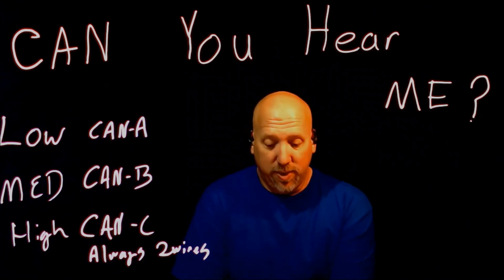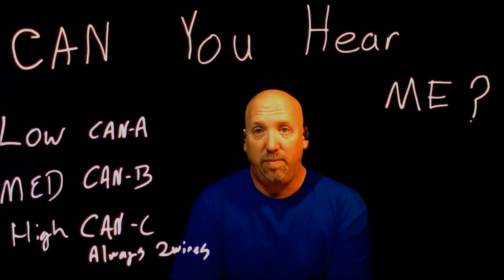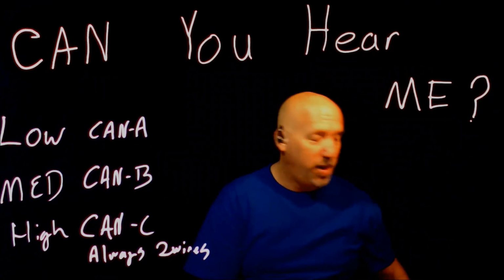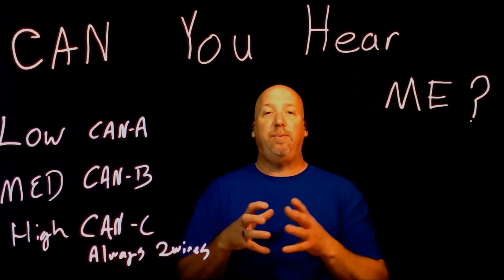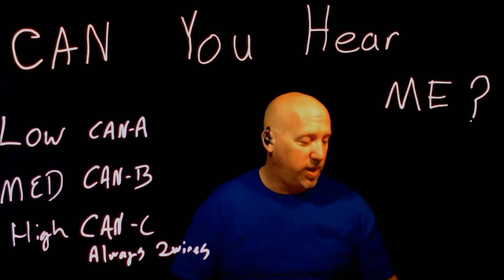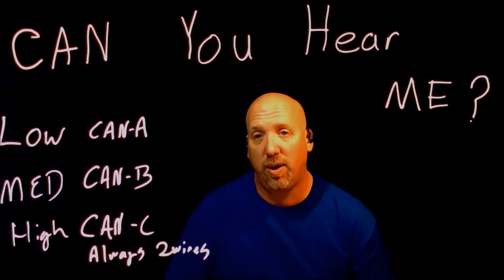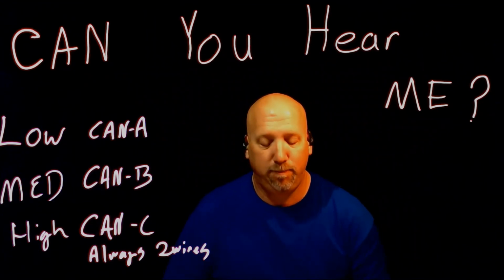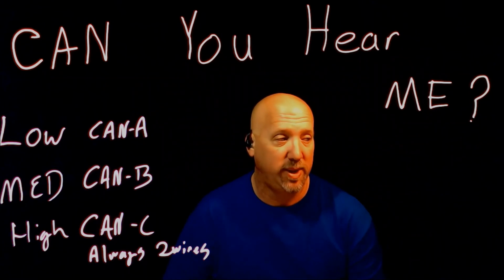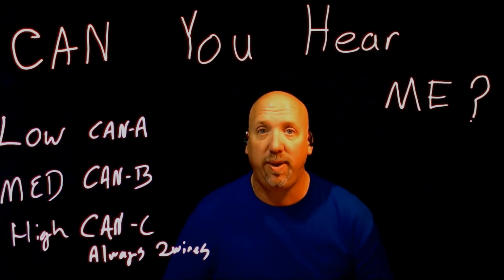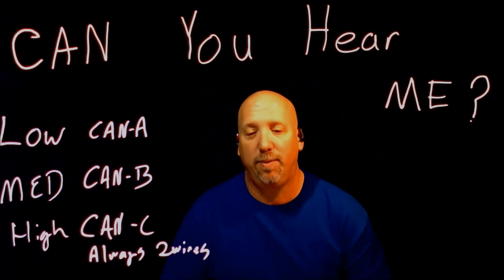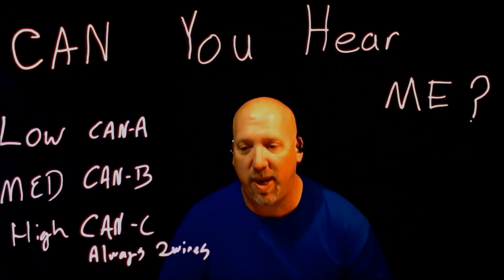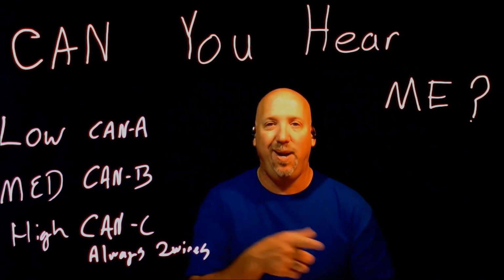Faulty CAN modules are generally designed to sign off the network if there's a problem. So if you've got a module that went bad, it's pretty much going to just shut down and not work. A lot of times you don't have communication with that module because it is shut down. Or you have a module that's basically gone to sleep permanently. We've had that happen a couple times where there's just no information from the data bus, and you check, and it all leads you back.